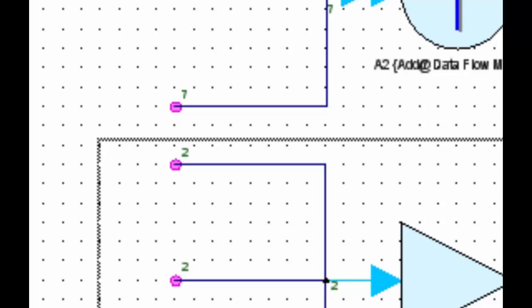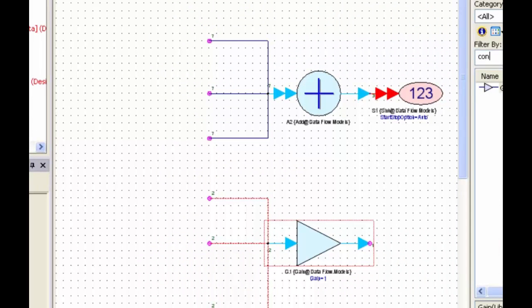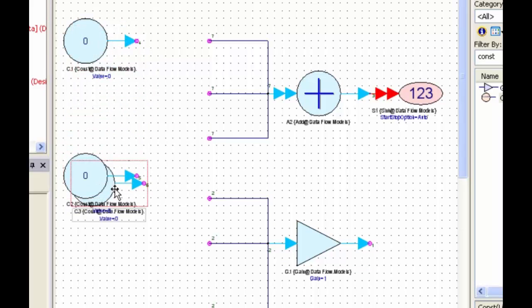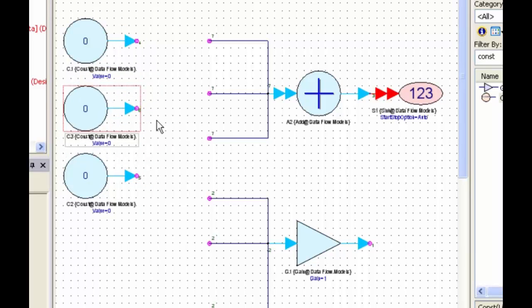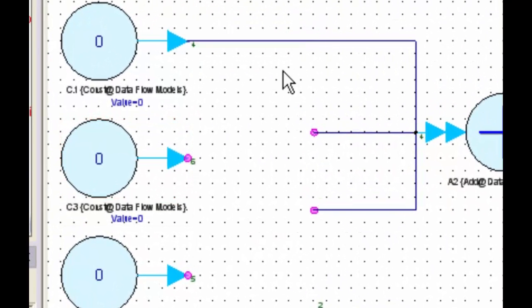However, unlike the single input part, if I now connect multiple source models or multiple wired connections to this input, you will actually see that the node names will change to reflect the fact that the input port of the multi-port part is expanding. So I'll wire this first source to the first wire, and immediately you see the node name change, so it's now picking up a node 4.